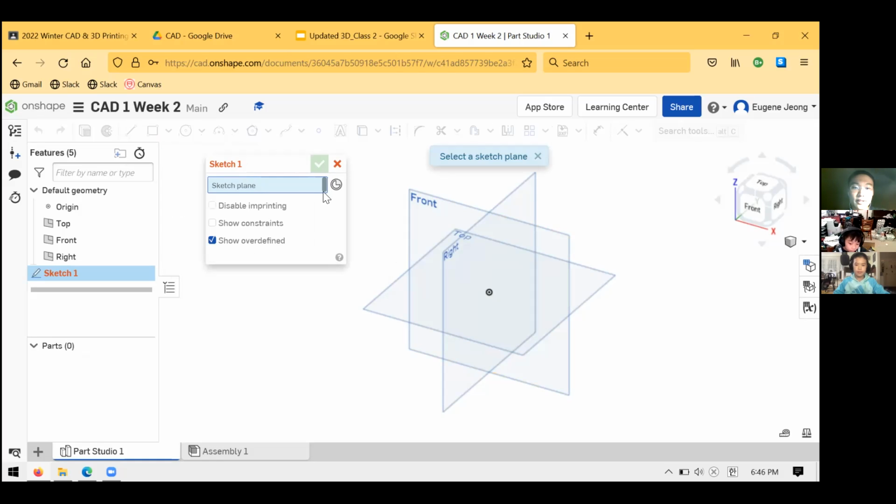And you'll see the first thing it draws your attention to is this highlighted box in blue that says sketch plane. And it's telling you, where do you want to make this sketch? What all these words mean, what planes mean, what sketches mean, it'll become more clear. But for now, just stick with me for a second. The sketch plane is going to be what surface, what direction, where you want to draw the sketch. Like, where is this piece of paper if you're trying to draw this sketch in a 3D space?